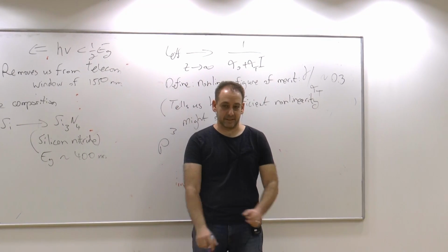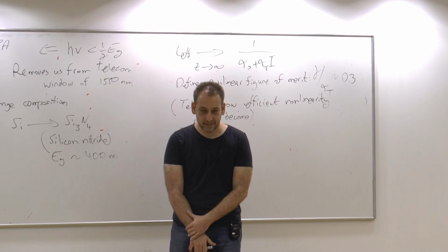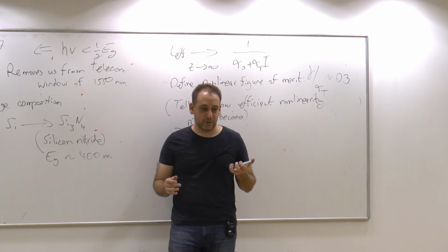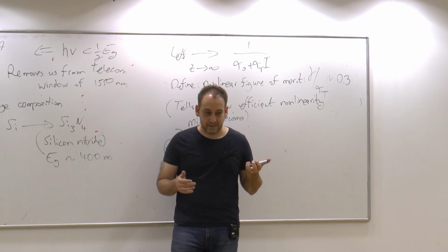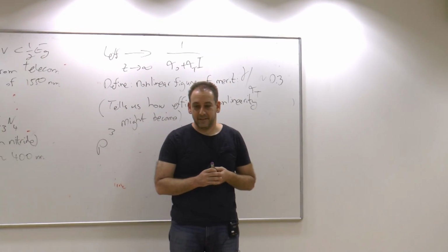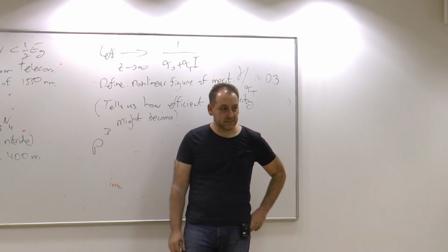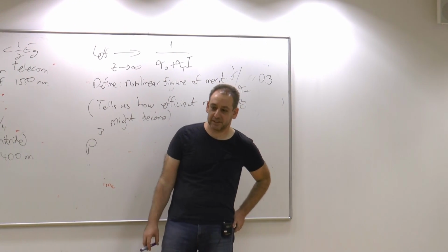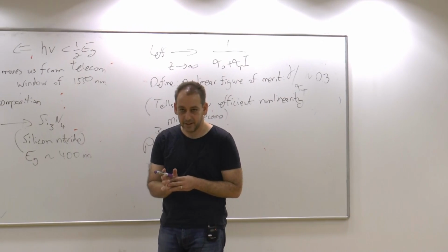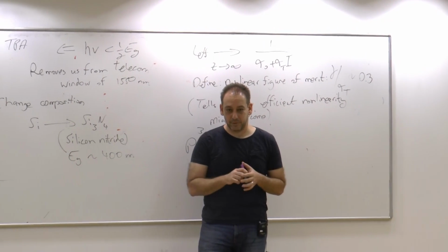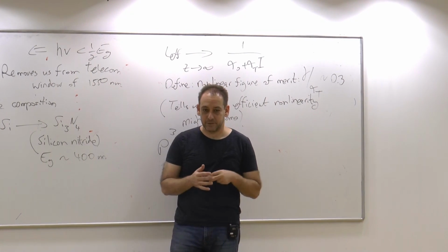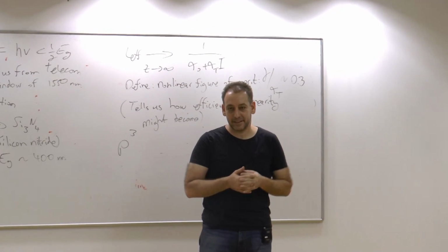Semiconductor laser diodes happen in indium phosphide, they happen in gallium arsenide, and some more esoteric alloys if you go to longer wavelengths. And this is all for a very good reason: direct band gap. I may or may not have said something about it in the first week, but we'll not go into detail now. The minimum of the silicon conduction band and the maximum of the silicon valence band happen at very different K values, very different momentum values. The difference in momentum is just too big for a photon to bridge. And therefore, stimulated emission or radiative transitions between bands in silicon are extremely inefficient.